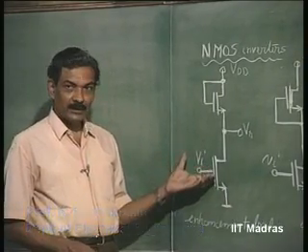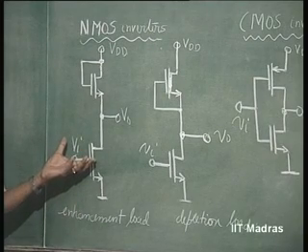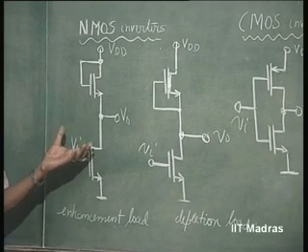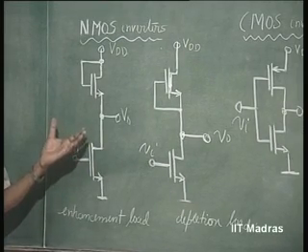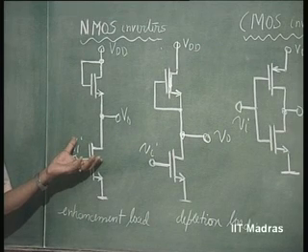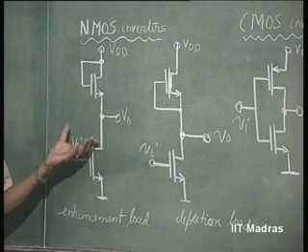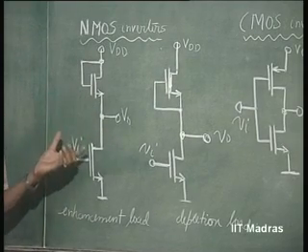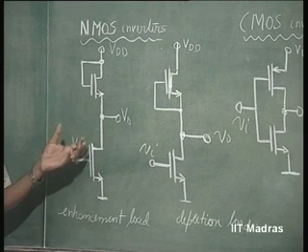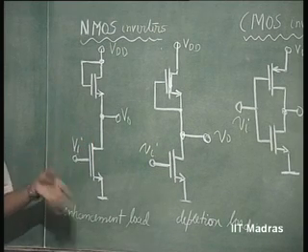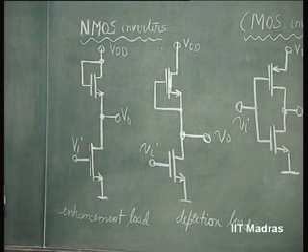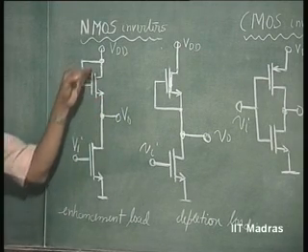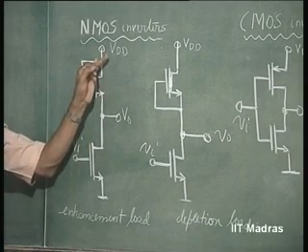The MOS technology is the simplest technology compared to the BJT technology. The number of steps for the process of fabrication is minimal. That increases reliability of such circuits enormously. Now, in such MOS circuits, the density of packaging can be increased considerably if we do not have any resistors at all. The resistors are replaced by MOSFETs connected suitably.